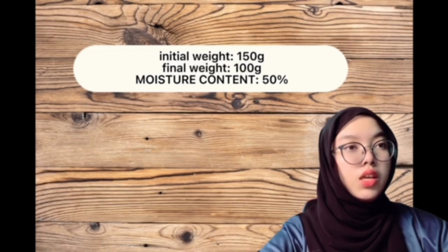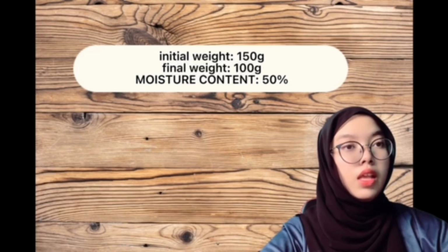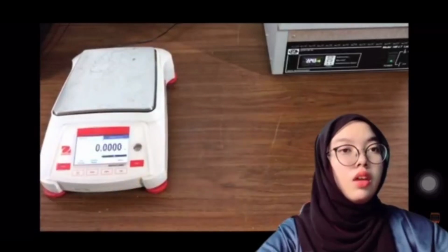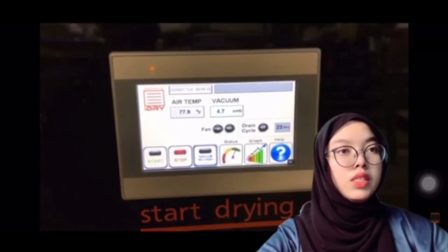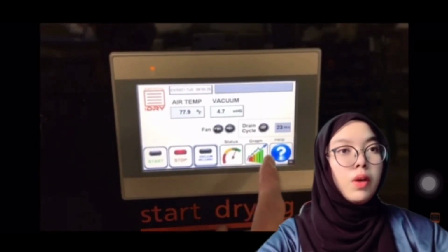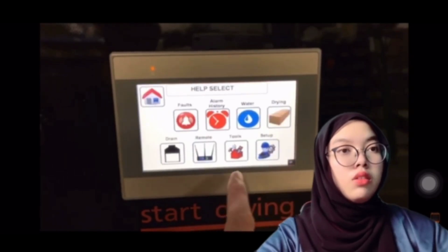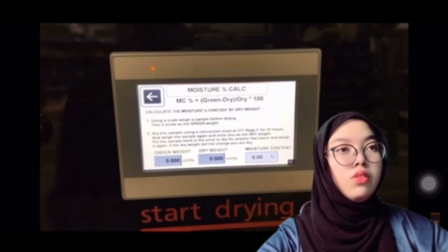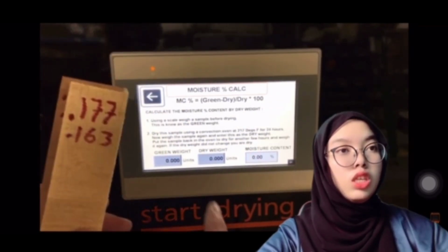So, the oven dry test can be a useful tool not only for verifying the readings from electronic moisture meters, but also for understanding what is happening inside of the wood as it dries. In some cases, even the oven dry test can be in error if the wood contains a high concentration of volatile compounds other than water. The correct moisture content is important for product quality, and the oven dry test is an important QC tool.